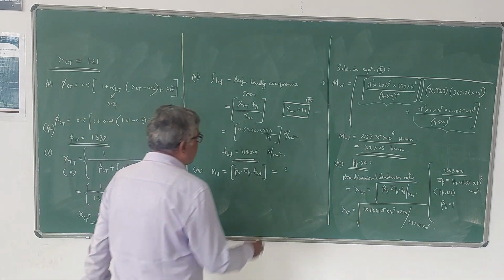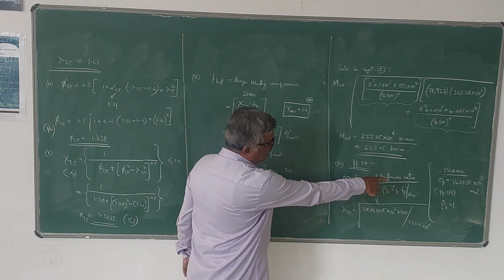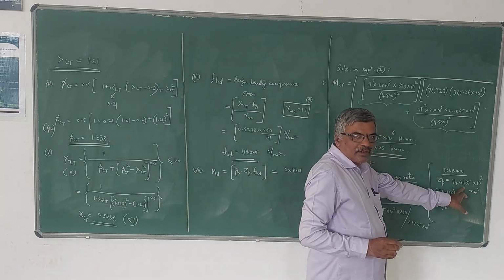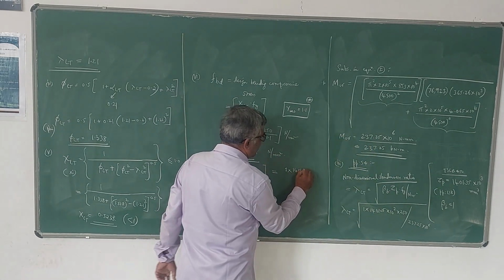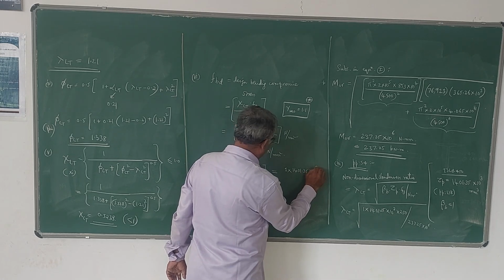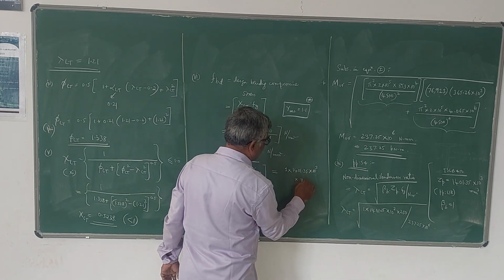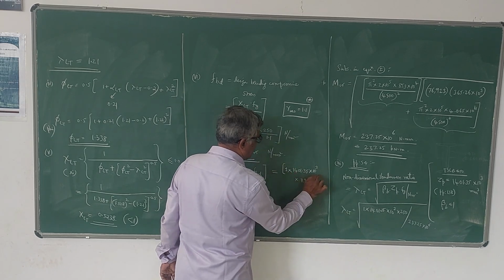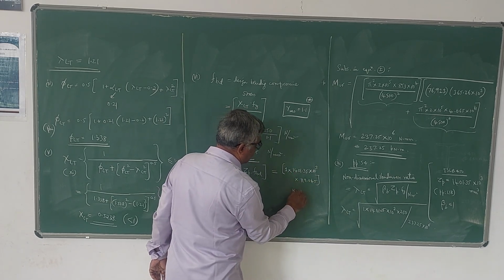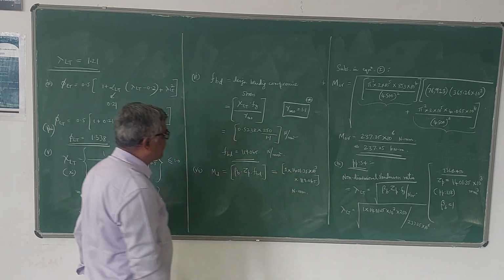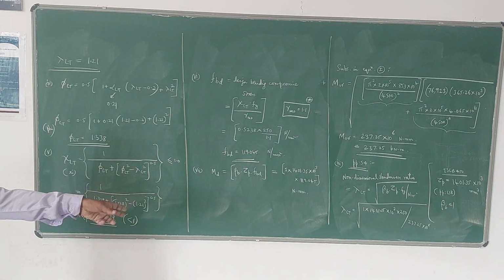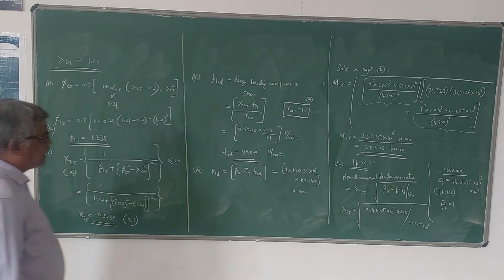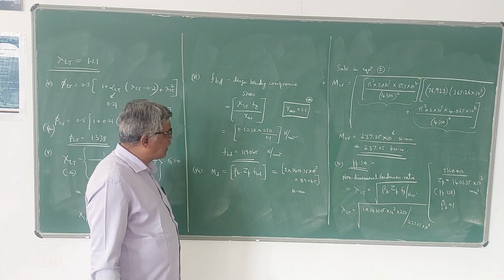Look at that. 1 into the ZP value, how much is it? 1401.35 into 10 power 3 into the FBD that came, 119.045. So you have to multiply all these three. This value will be in Newton millimeter units because it is a moment, the design bending strength. How much does it come to, the bending moment?